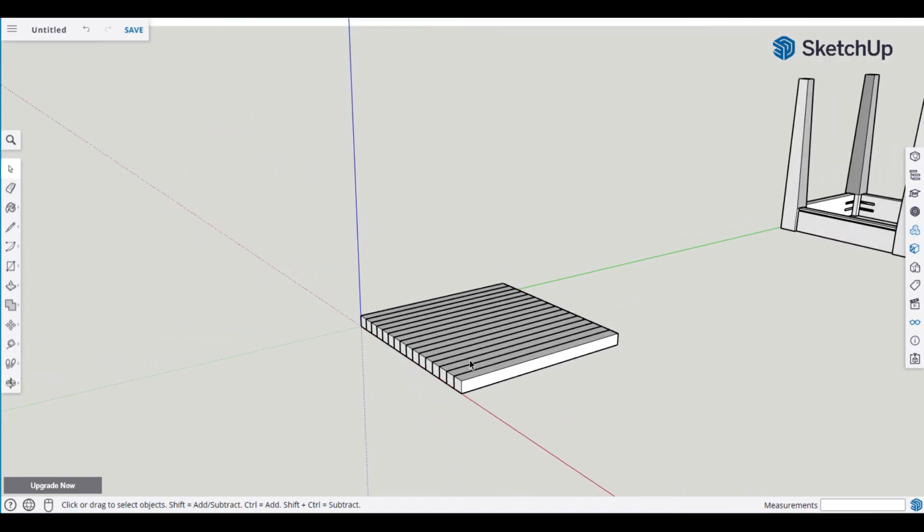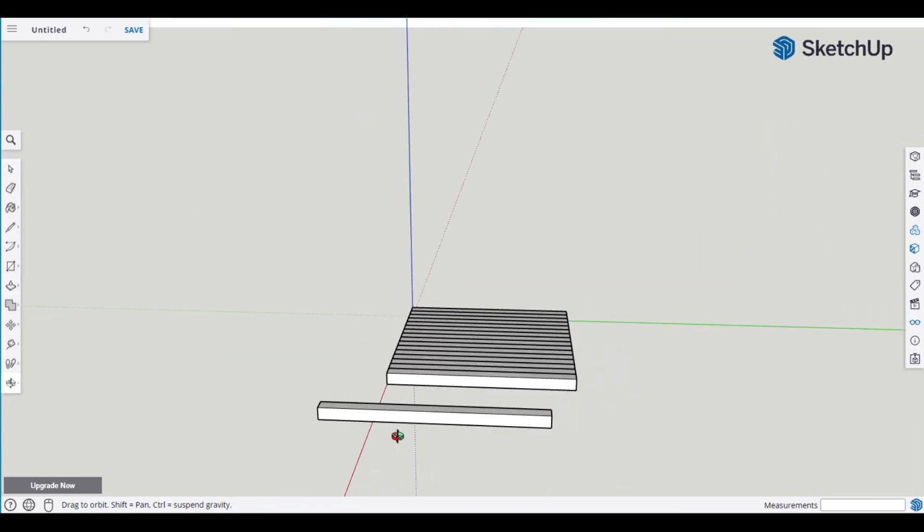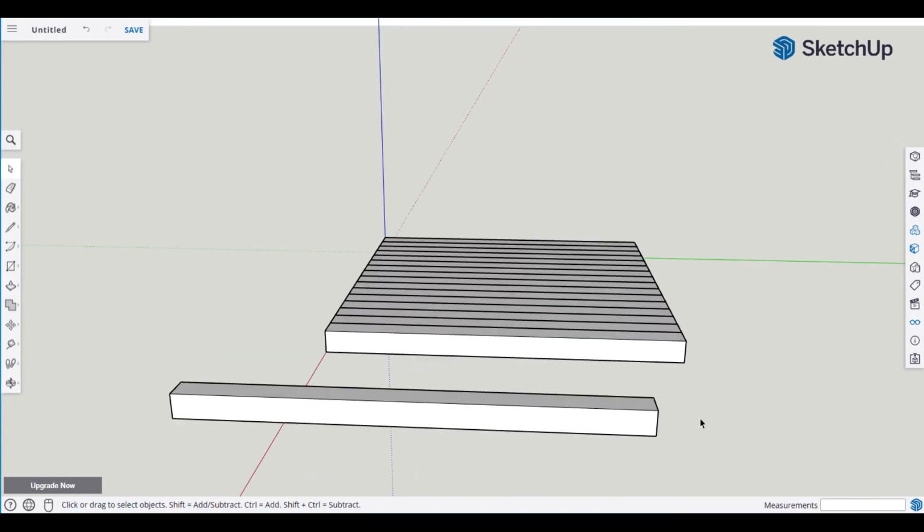Next we're going to create our edge border, and we're going to do miters. So this is going to be 18 inches. Each new strip is going to be 18 inches. So now we have to create a rectangle. Doesn't matter where we do it. We got it. So we can see the first dimension is going to be the width. So that's going to be 1, 18, enter. Select the P, highlight, pull up, type in 1, space bar. And now we have our edge border.